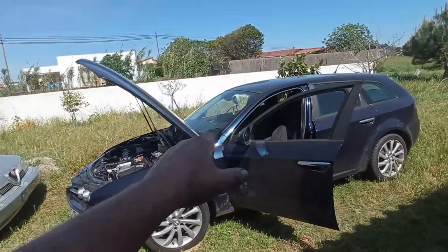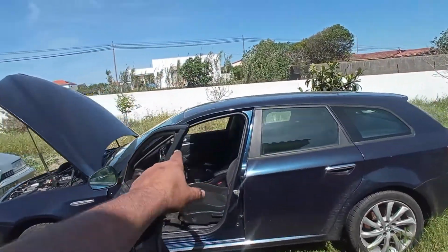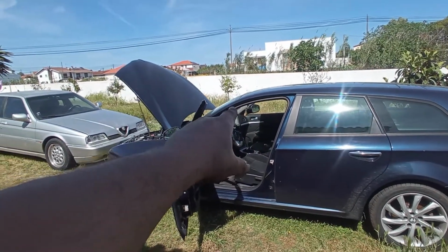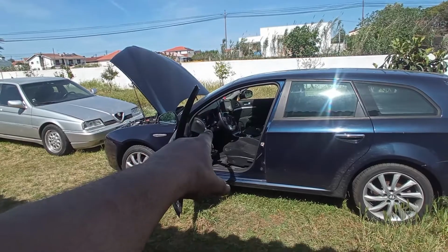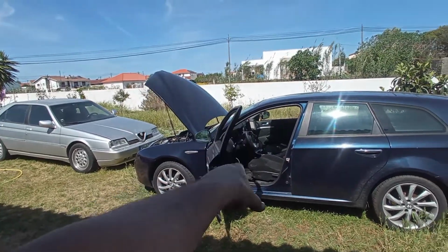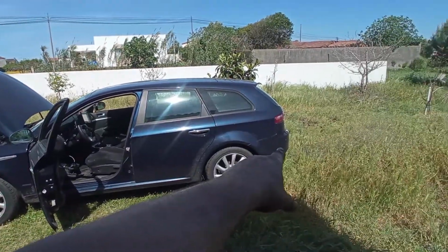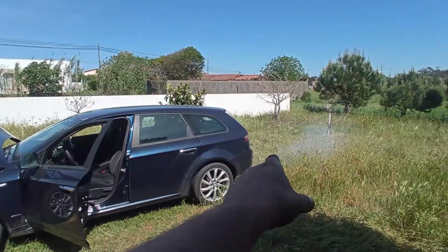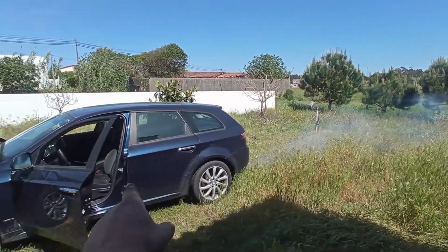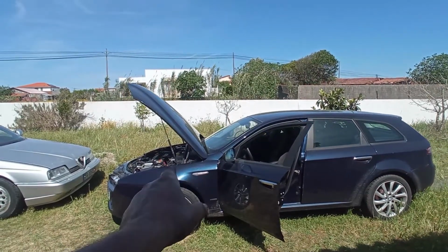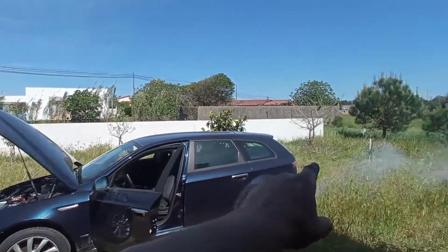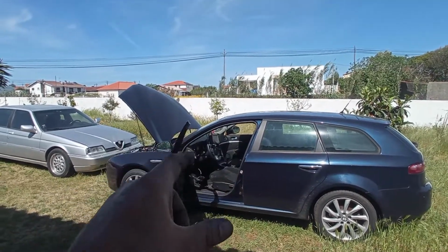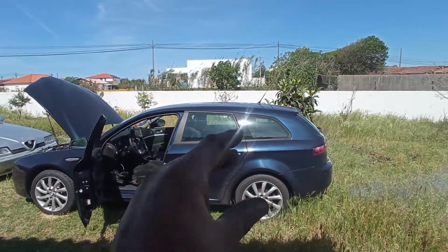Okay, just now I pressed OK after the temperature on the diagnosis machine was up over the 70 degrees. Now the car decided that it's secure to do a regen, so it's doing that for me. As you can see, there is oil. As you can remember, this engine has a little bit of blow-by, okay? There is oil, not diesel. So after this, the car will stop to do the forced regen.